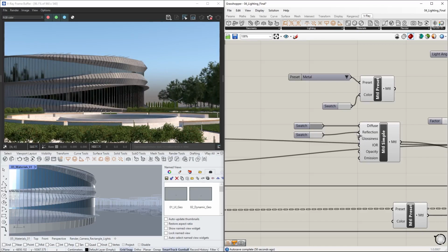The glossiness parameter controls the sharpness of reflections. It takes any value from 0 to 1, with 1 resulting in sharp reflections and decreasing it resulting in blurrier reflections. Set a value from 0 to 1 with 2 digits after the decimal point. I'll set it to 0.75.